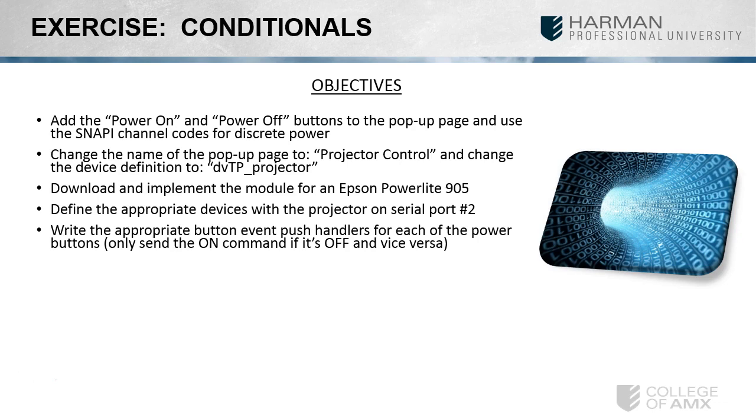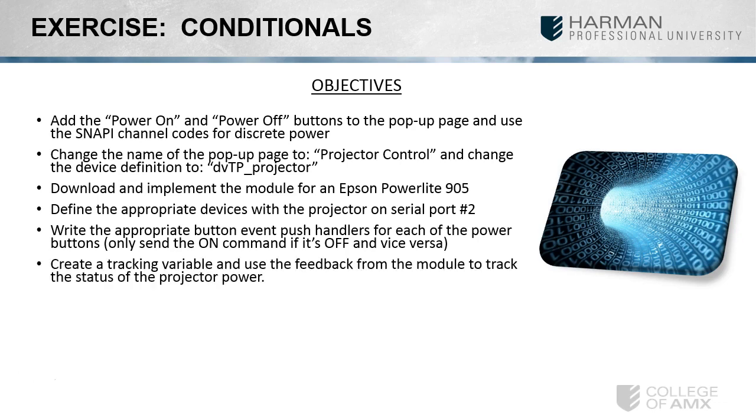The projector lift should be tied into the projector power state. The reason for this is so it's not possible to have the projector on and the lift up in the ceiling, potentially creating a fire hazard.